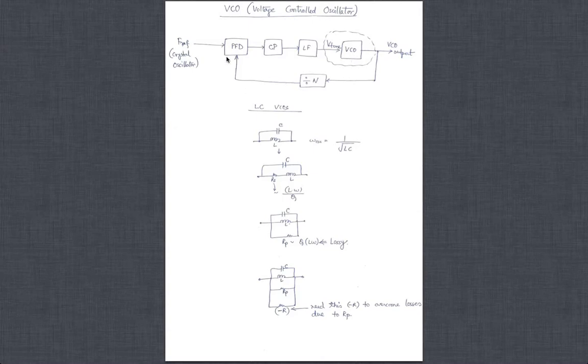So here is a PLL block diagram. We start from here, which is called FREF. FREF is a reference frequency. It mostly comes from a crystal oscillator. This is a very accurate frequency reference, which is off chip, and has extremely high accuracy. So you can generate an accurate clock, which is our output here. This is the frequency we're trying to generate as, say, the VCO output. You have to have some sort of accurate input, right? And that input is this. So from the crystal oscillator being accurate, we are trying to generate an accurate output here.